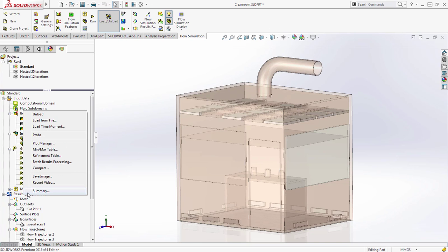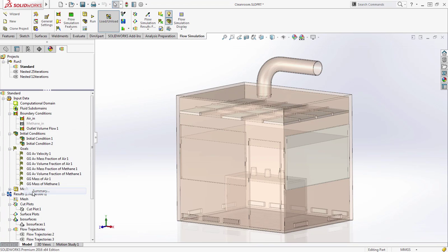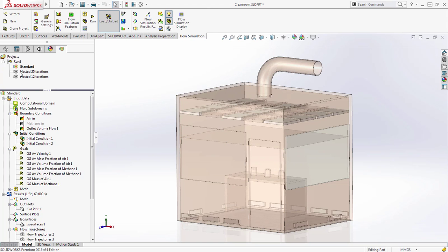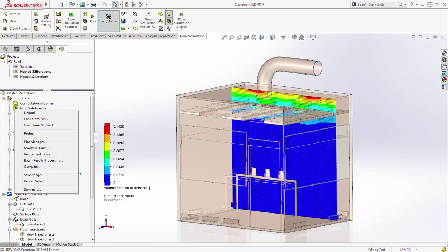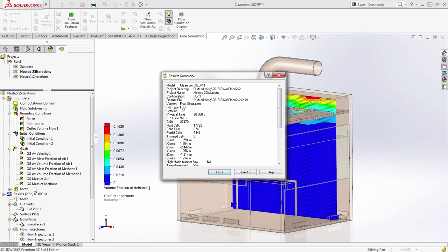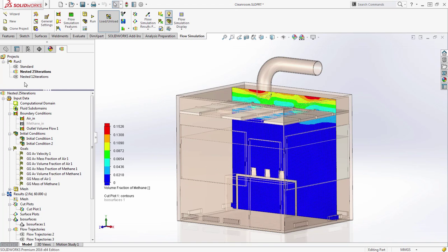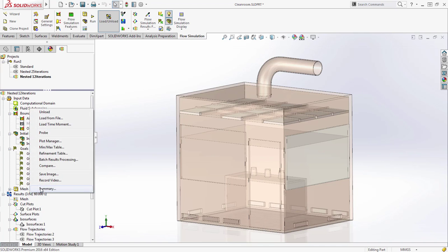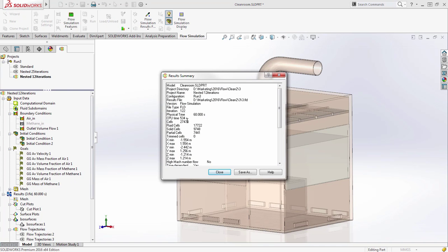To compare performance, we can take a look at the solution time for all the 3 different studies. The first study is using the default settings of the solver. We can see it took 1300 seconds roughly to finish. With the nested iteration control set to a maximum of 25, that comes down to 970 seconds, or a 26% time reduction. With the nested iteration maximum set to 12, this further reduces to 534 seconds, or a 59% reduction.